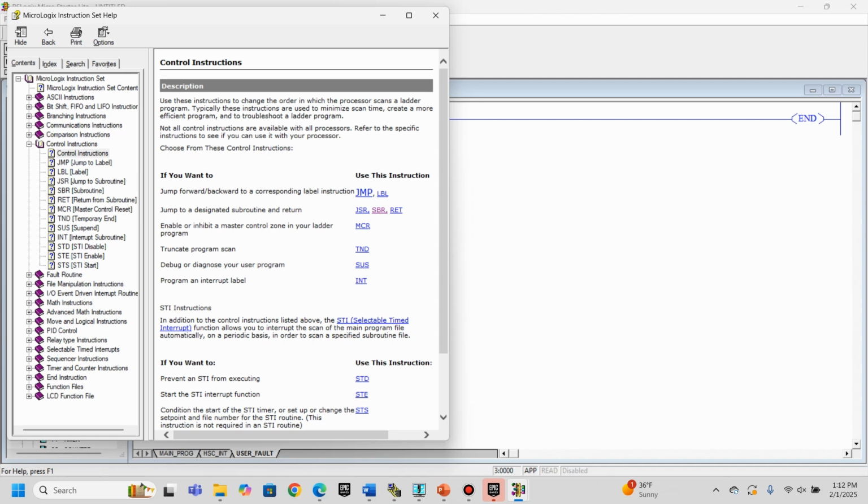I know when I first started programming, I used to think you put everything in the same ladder file, like ladder 2. But that's actually kind of poor programming. You want to break up different functions and put them in different routines. It makes for a lot cleaner code. And we're going to go into that a little bit further.